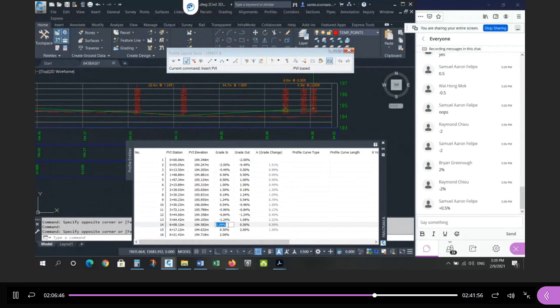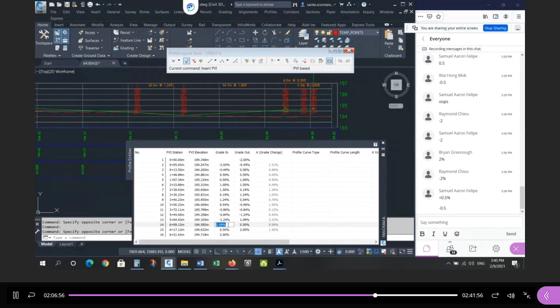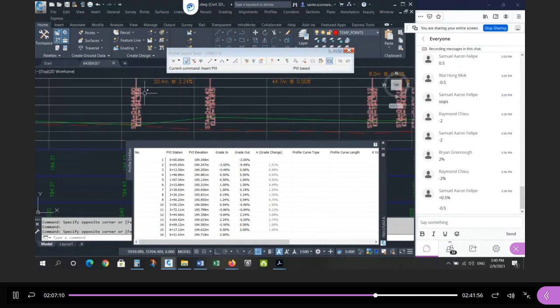On the straightaways, I'm going to use the minimum slope. What should I type in here? Exactly. So it's still going to be percent, but now we're going down to the low point in the direction of increasing chainage, negative 0.50%. And you can see that. What was the minimum slope? This tangent is the beginning to the end of the curve. What slope are we going to use there?